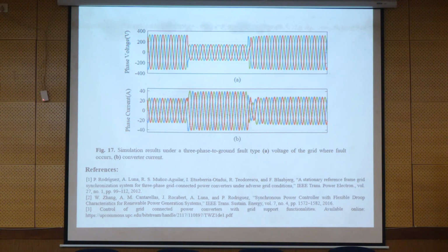Inertia part, maybe the ground is sufficiently supported. Any other issue? Okay. One aspect is the inertia. It means that when the inertia is not enough, you have the problem for the frequency changes. But then the other is that this type of distributed generation system also provides harmonics for the grid, and also increases the impedance of the grid.